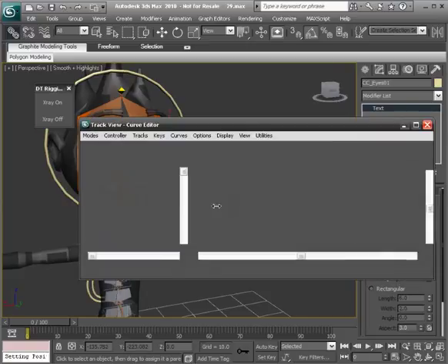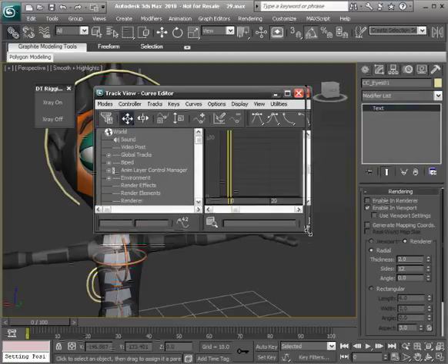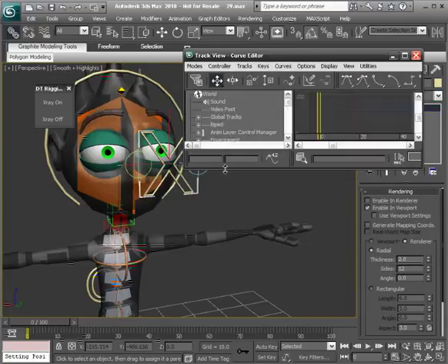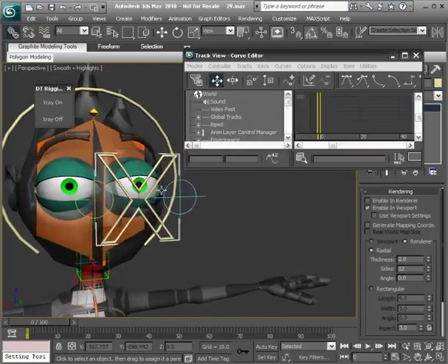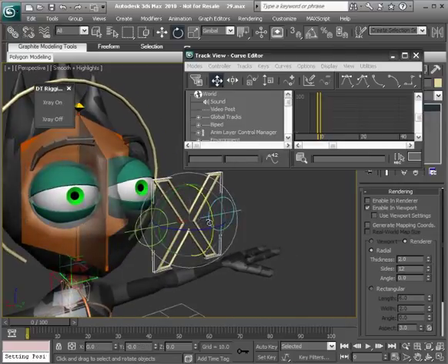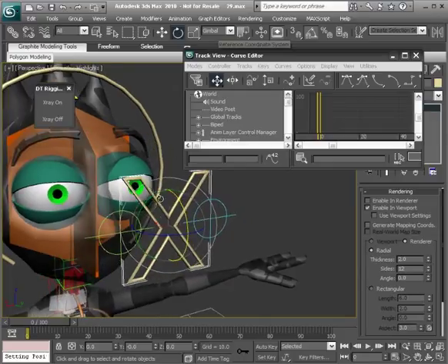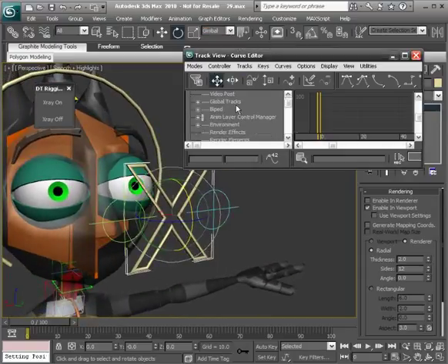Head over to the curve editor and start to lock the attributes or the controllers that we don't need to worry about. So for this one, I actually like to keep the rotation Y and also rotation Z, because that creates a type of googly eye effect. But the X we can get rid of. Alright, and we want to make sure we're under gimbal mode when we see this, so we know the actual axis that we'd like to remove.